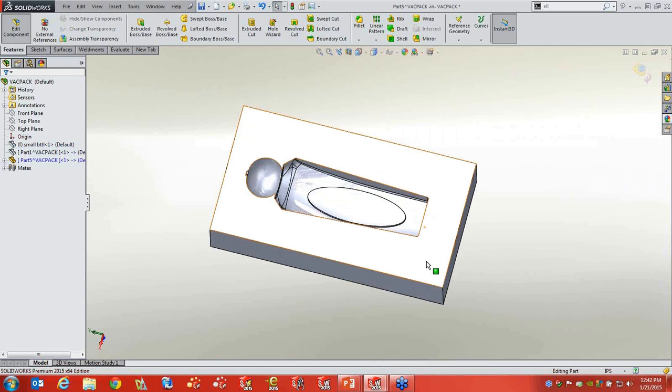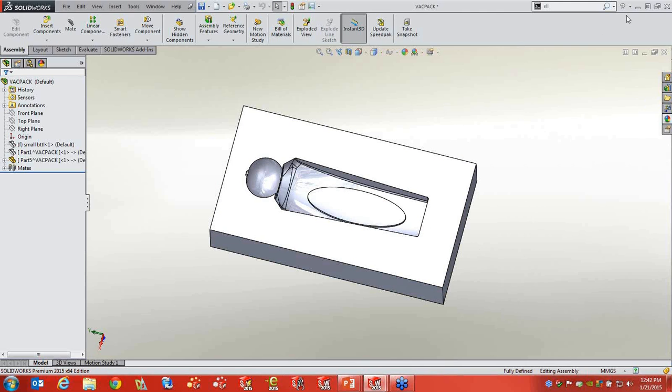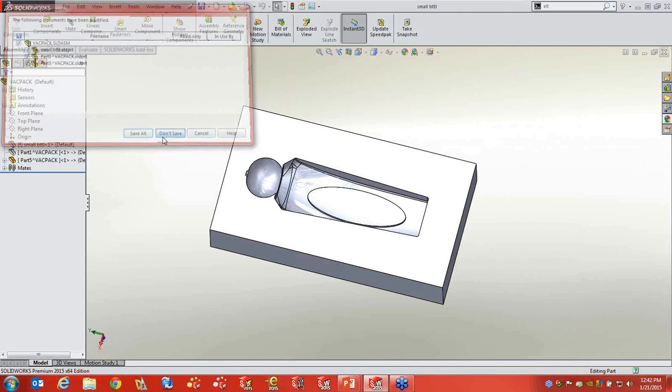So this is how molds used to be done in SolidWorks, but the cavity command is still there. I guess what I've used it for in the past is any kind of tooling, let's say, where you need to create a place for a part to fit where there's kind of a cutout. You can utilize the geometry of the part and create a cavity of it. It's kind of like the indent, isn't it? It creates a void in the area, but you do it inside the assembly level. So cavity, it's there. Maybe you haven't used it in a while.